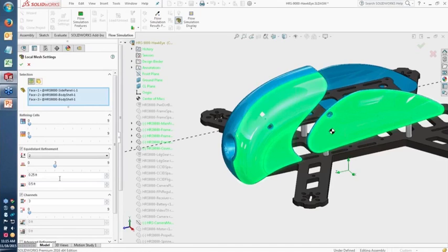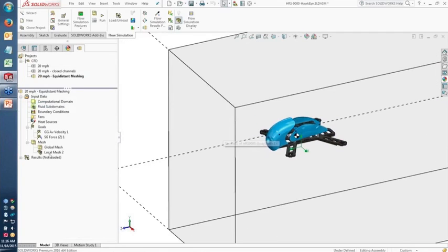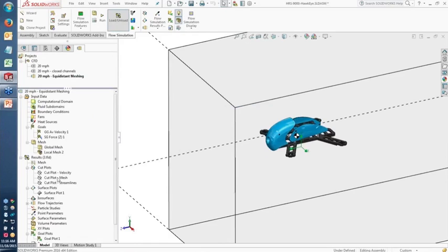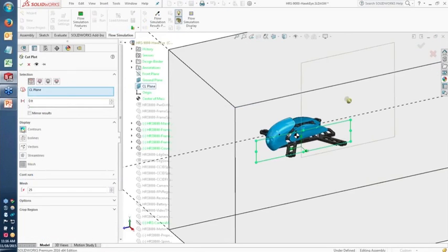And when I generate the mesh, you will see that there are basically these two regions of extra refinement in a similar shape to the faces that I've picked here with that extra level. And it will always be one level of refinement difference between each of these zones. So when I go to generate this mesh, you can load in the results here. And let's look at that mesh cut plot again, this time just with the mesh, no velocity or anything.